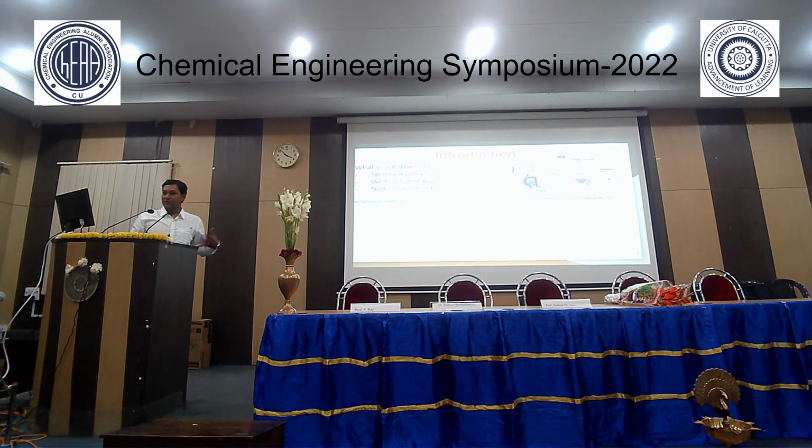In order to do that, we first need to understand how nucleation growth occurs in a solution. Whenever we are doing the reduction, individual atoms will be generated in the solution, and they will agglomerate to form a nucleate. That nucleate has to be of a certain critical radius, and only then will it grow, otherwise it will dissolve back again. That is again the surface energy phenomenon.